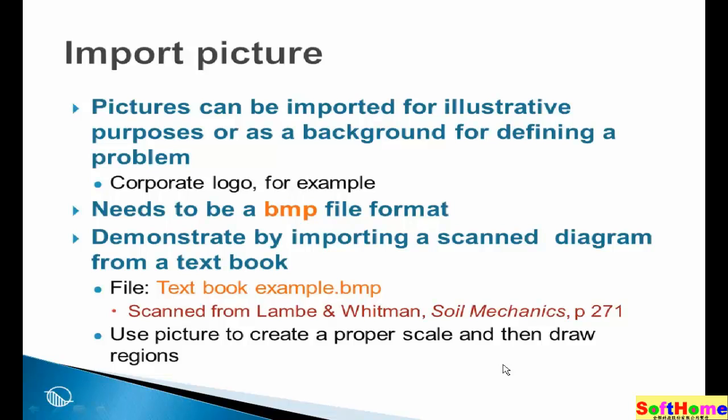Pictures can also be imported into GeoStudio. Pictures can be imported for illustrative purposes or as a background for defining a problem. For example, you could import a bitmap of your corporate logo and put it on the drawing. It is important to recognize that it needs to be a bitmap file format. A JPEG, for example, is not accommodated by GeoStudio, so it has to be a bitmap file format.